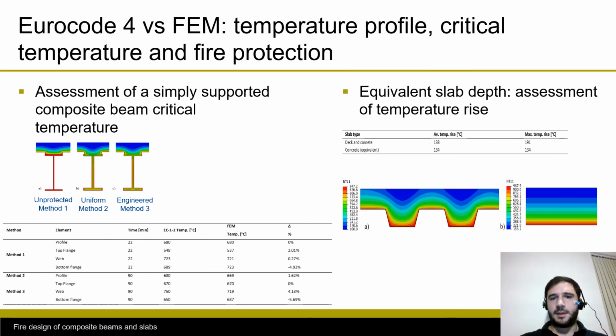So a numerical simulation was completed to evaluate if the temperatures imposed by EN 1363 Part 1 to fulfill the thermal insulation requirements are fulfilled with such equivalent depth, and it was concluded that the maximum temperature rise criteria may not be fulfilled while considering the minimum effective thickness given by Eurocode 4 1-2 Annex D. For this reason, there are other documents that suggest a different approach, perhaps more derived for specific products, specific decks, specific composite slabs, as we have in the UK with the NCCI.